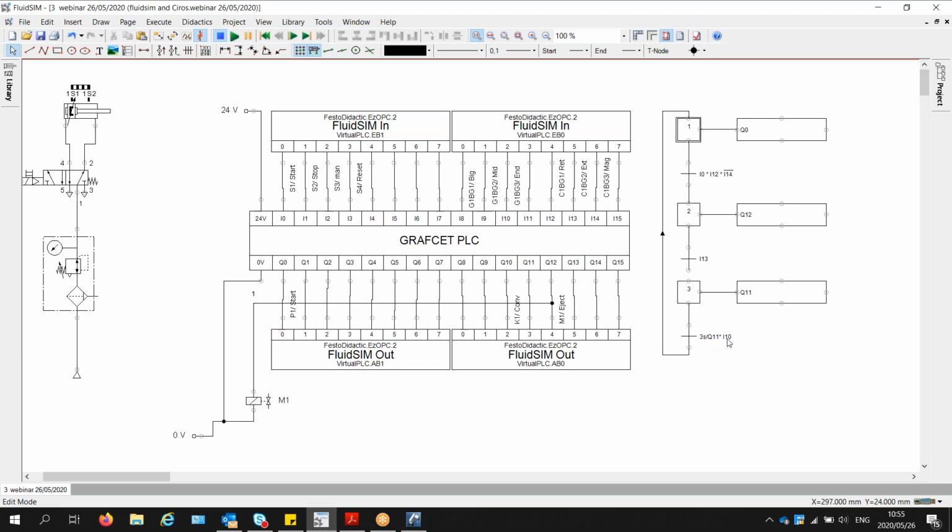And I'm using input 10 as an end condition. And input 10 is actually a high state of the light barrier sensor at the end of the conveyor. We know that if there's no workpiece at the end of the conveyor, the input will be high. If there's a workpiece, it will be low. So that if there's a workpiece at the end of the conveyor, we do not stop the conveyor up until there's no more workpiece on the conveyor. Now this needs to be tested.